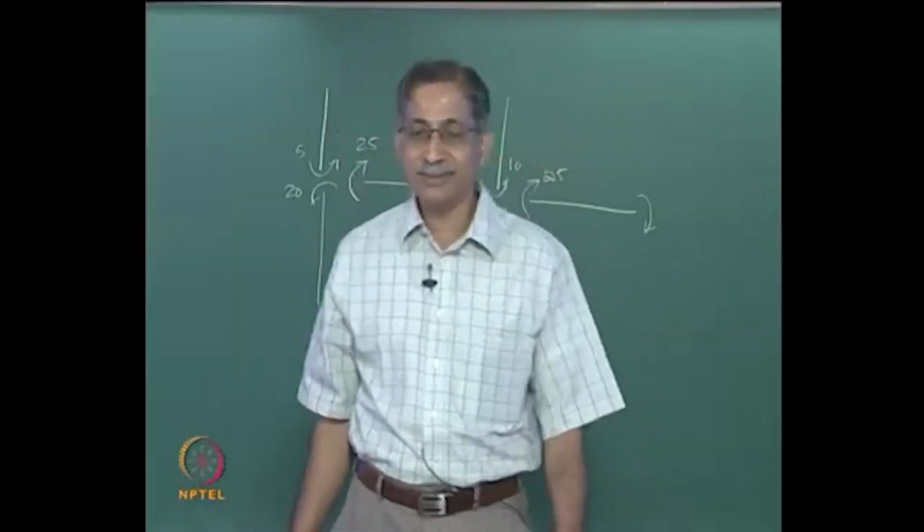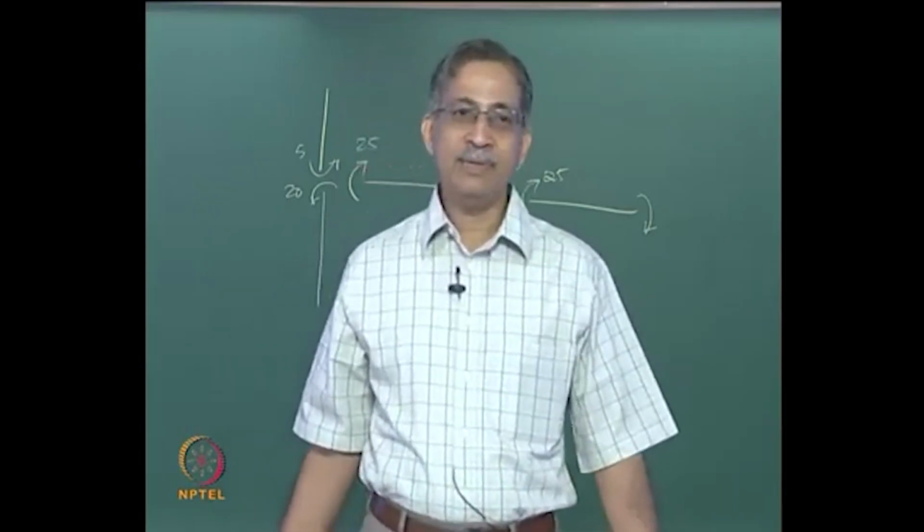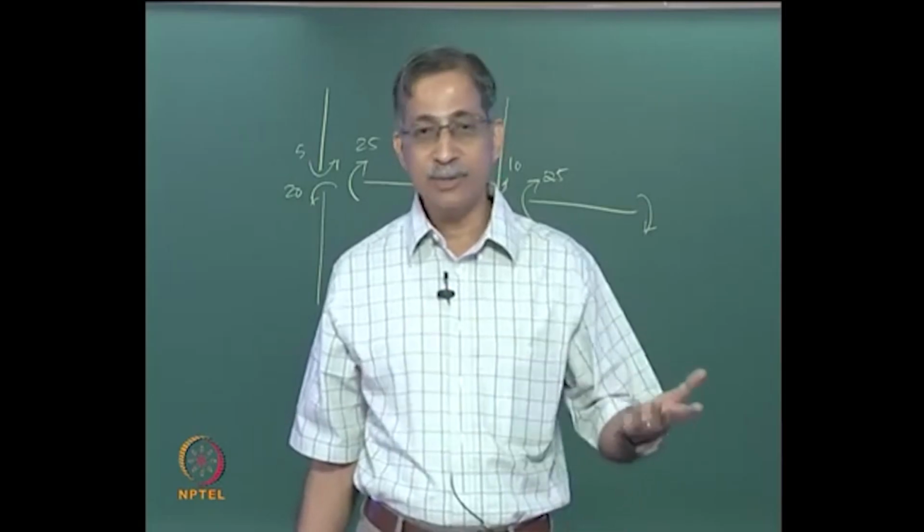Add the 2 end moments in the beam, divide by the span of the beam. So that's right. You guys are good, you can do this. So what do you get? 5 into 2 divided by 3 is 3.33. You got all the shear force in the top.